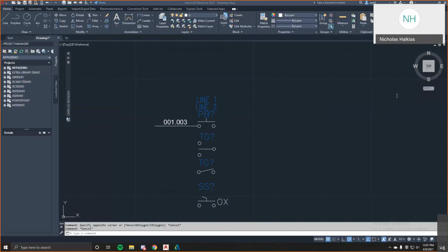Okay, so for example, in Multisim, you can put a button connected with a wire to a source, connected to ground, to an LED and then ground. And then in Multisim, you can run a simulation, click the button, and the LED would turn on, right? Now, you could use Multisim. You could print out the page, send it to your technician and say build this. You could do that.